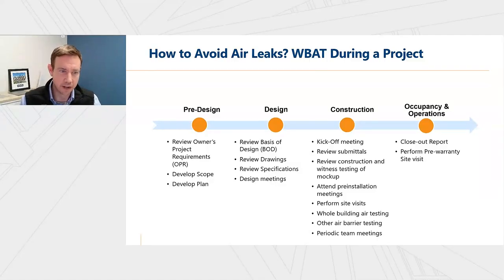Again, in the design phase, the review of construction documents. Trying to catch any potential issues early in the design drawings and specifications first is beneficial. For example, verifying that there is a dedicated, defined, and continuous air barrier.